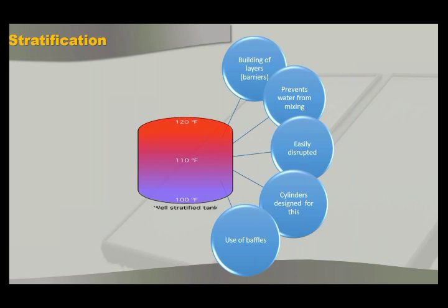This isn't a heat pump course, but I'll just say very quickly that a big problem when guys install heat pumps is they don't install a means by which to control the stratification or the disruption of stratification. Some manufacturers want diffuser pipes, others put mixing valves in, and so on. And it is a hell of an important thing to consider.